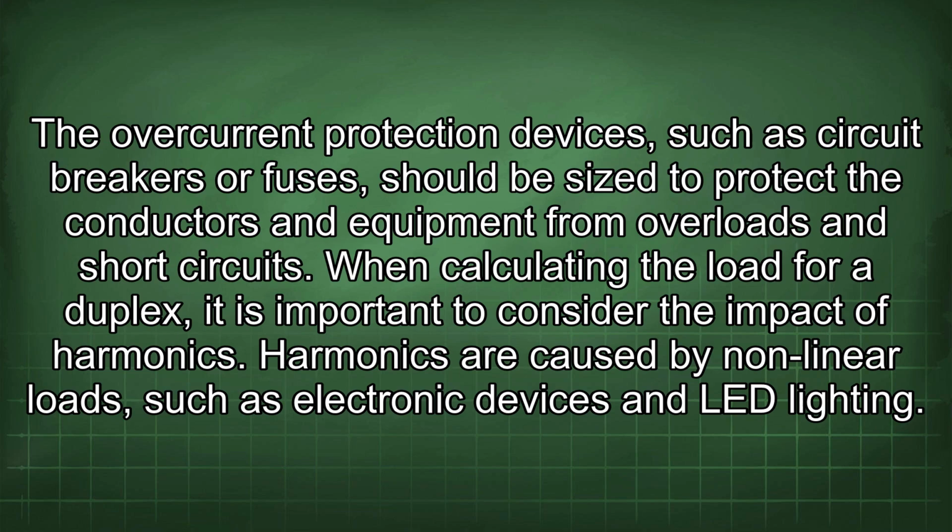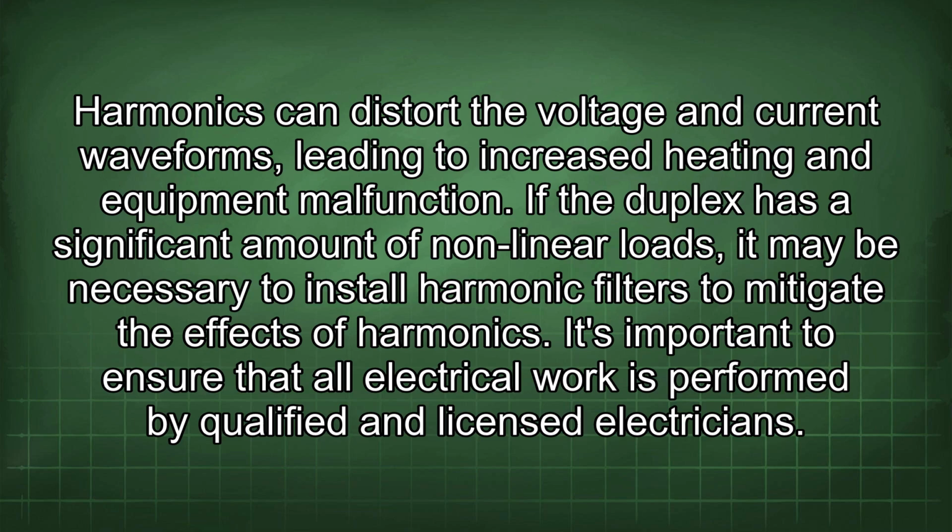When calculating the load for a duplex, it is important to consider the impact of harmonics. Harmonics are caused by nonlinear loads, such as electronic devices and LED lighting. Harmonics can distort the voltage and current waveforms, leading to increased heating and equipment malfunction. If the duplex has a significant amount of nonlinear loads, it may be necessary to install harmonic filters to mitigate the effects of harmonics.